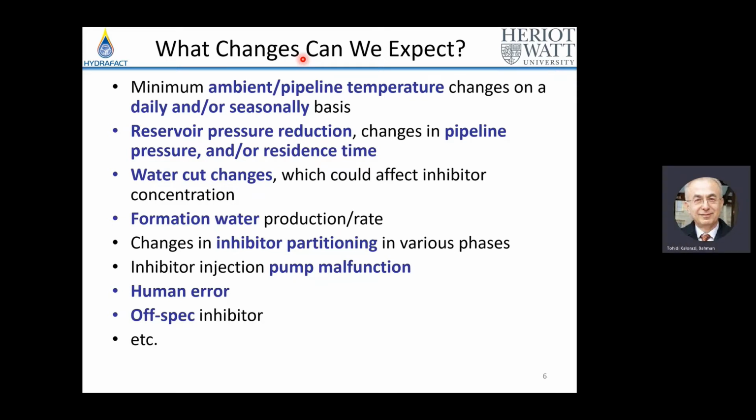Another important change is the water cut. It would affect inhibitor concentration. It is also possible that initially we have condensed water, and after a while we have formation water. Formation water normally has some salt, but condensed water could be almost salt-free.